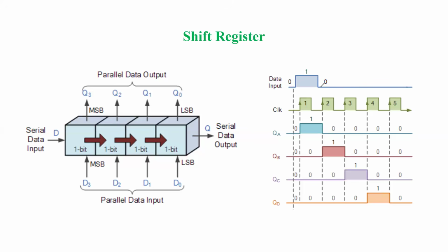So before that the input is 0, and by default the output of all flip-flops will be 0. But when data is available, like you are seeing here, data applied is 1 and the remaining data are 0. So it's going to generate a stream of bits where the initial bit is 0, the next bit is 1, and all successive bits are 0.